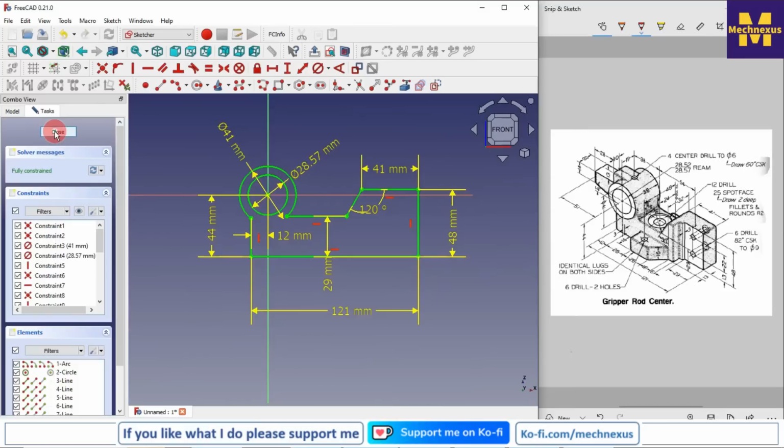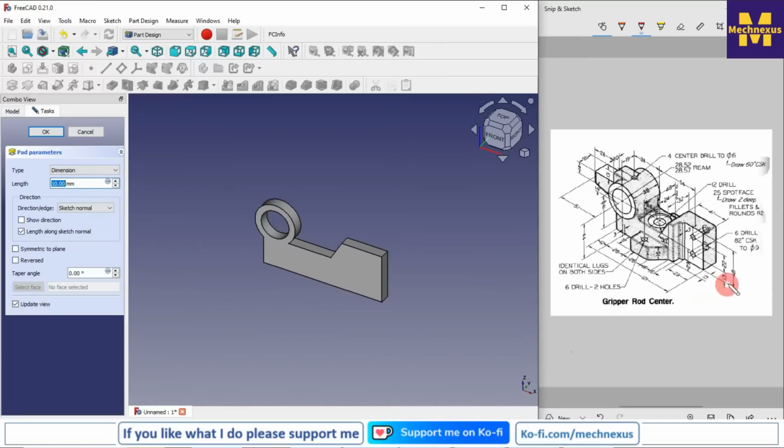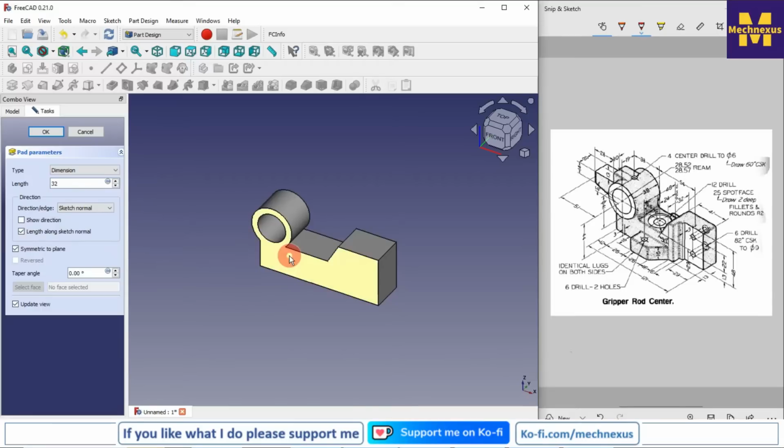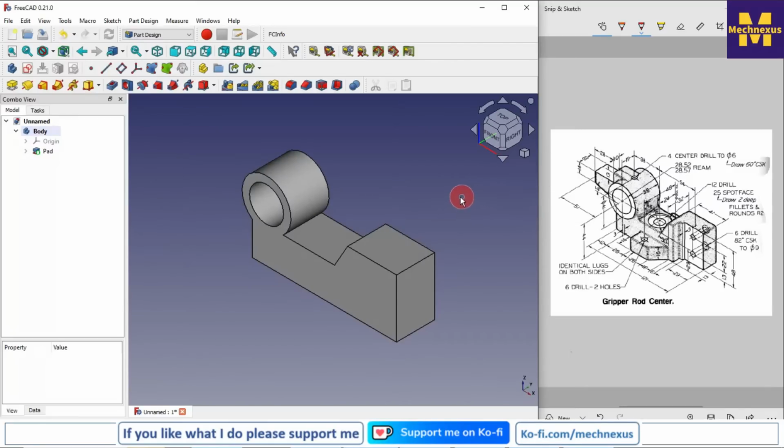And now I will close my sketch and click on the pad. In pad we can see here our extrusion length is 32. So we will consider the maximum material in extrusion and we will create this pad later. So here I will give 32 mm, and from here I will check symmetric to plane and I will click OK. So we have made our first base feature, and now we will move to the next features and we will read our drawing and sketch it.